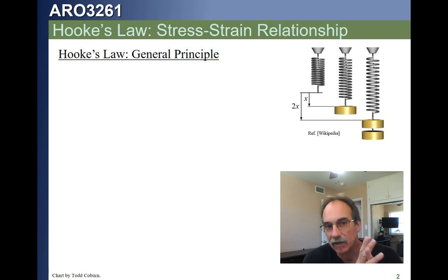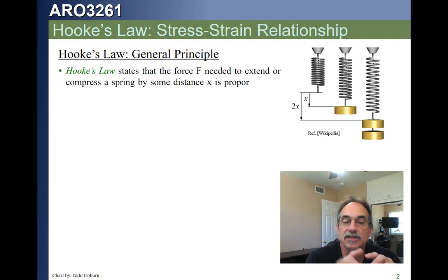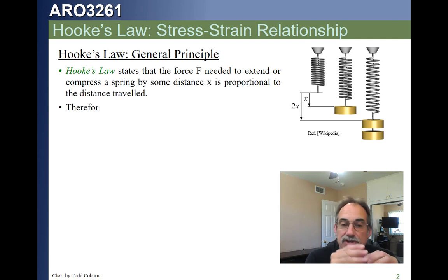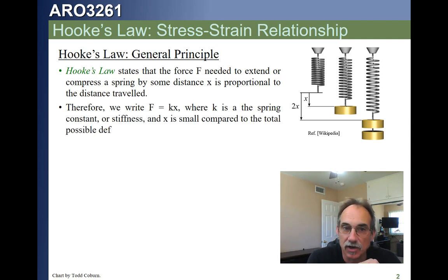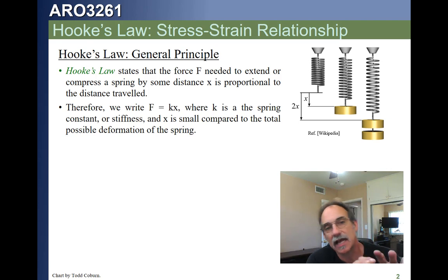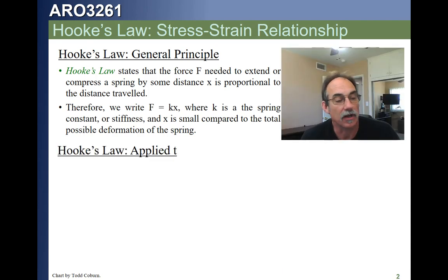Recalling what we covered last time when we looked at stress-strain curves, remember we saw that the slope of the stress-strain curve is just stress over strain. The slope of the load-deflection curve is just force over deflection. This ties back to a concept from physics: when a spring is being deformed, lengthened, or pulled on, the deformation of the spring times the spring constant gives you the force. This is called Hooke's law.